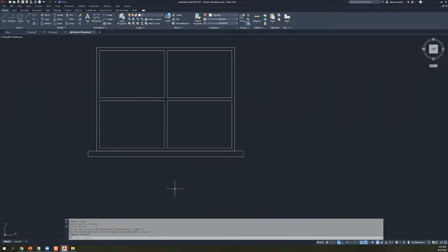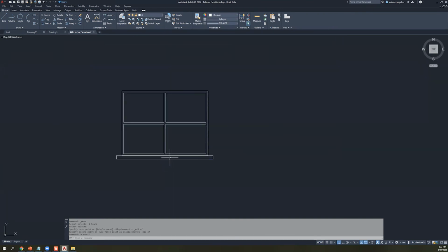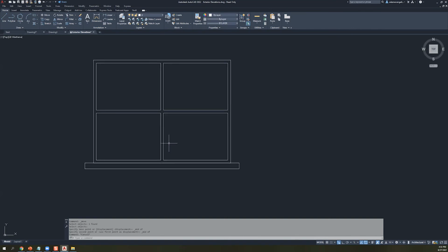And so it's a funny nuance there, because we're not technically choosing one object, the other object, and clicking the align button. I used to use Photoshop and Illustrator, for example, and there's a whole suite of align buttons in Adobe products, where you just click objects and they'll align along a center line or something. We don't have that benefit here, unfortunately. But what we can do is use our constraints and our snaps in intelligent ways. So snap midpoint on the move allows me to override and push it onto another midpoint for the actual window. And therefore these two are technically aligned along the vertical symmetry now, which is what we want.